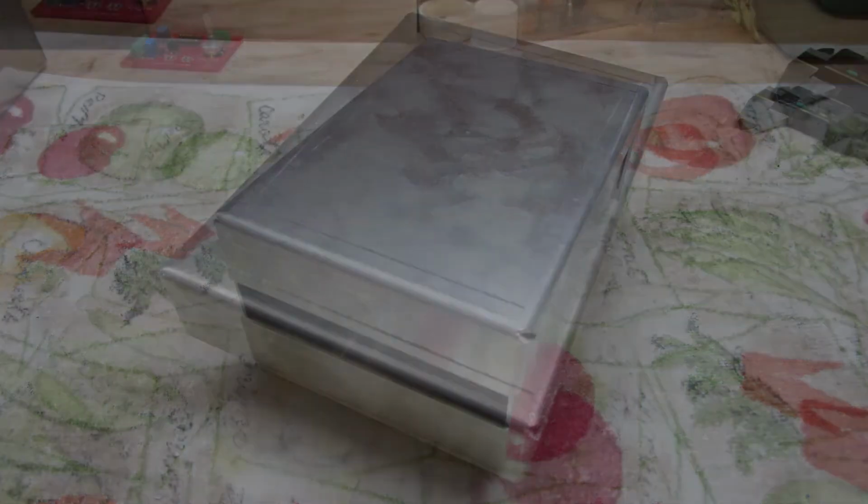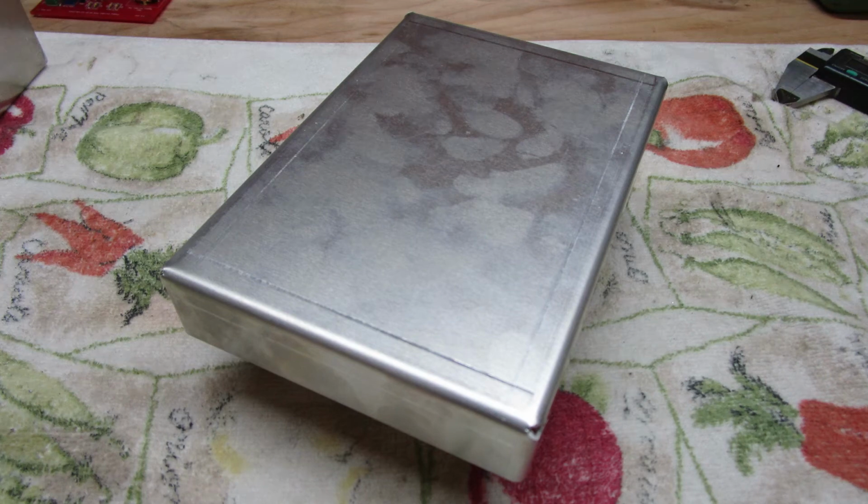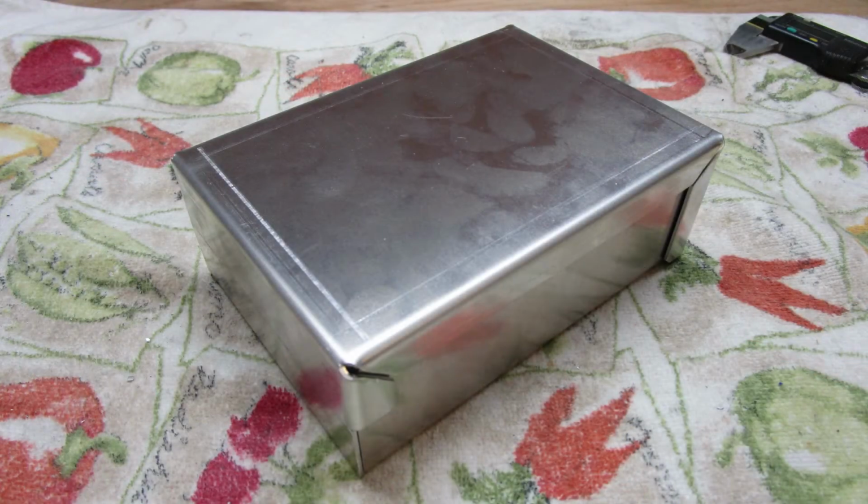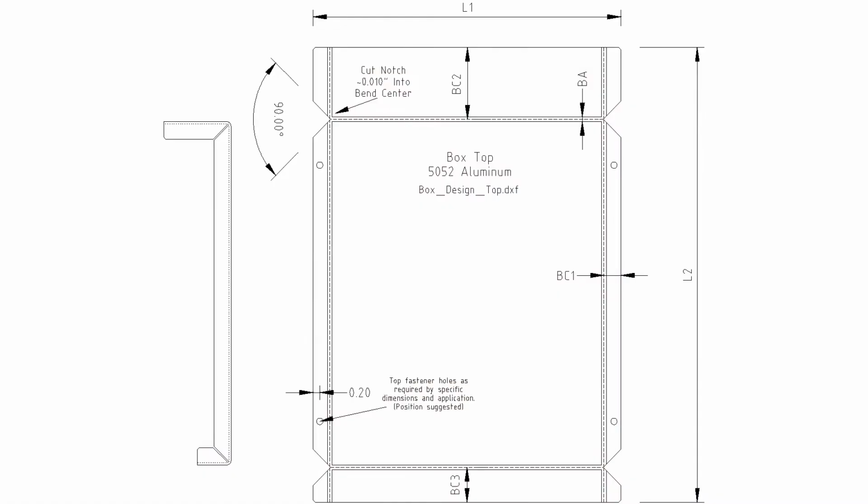My shop includes a Diacro press brake, which is what I use to bend sheet metal parts. The aluminum project box was a simple part to start making. It ended up with creating a 3D model after the fact. This video is the first in a series covering 3D modeling of a simple sheet metal box consisting of a bottom and fitted top. Bent parts usually start off with a flat layout, bend centers, and subtractive features like notches and holes. It's interesting to see all the details involved to make a simple part.